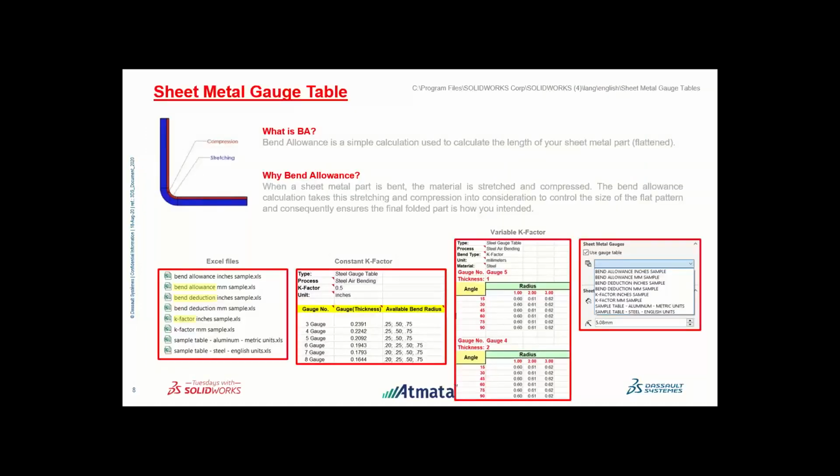Okay. One thing to remember is something called the bending allowance. I'm not going to talk much about this. Usually we have the bending allowance, bend deductions, and the K factor. As we bend the sheet, the neutral axis is not going to be exactly at the center.